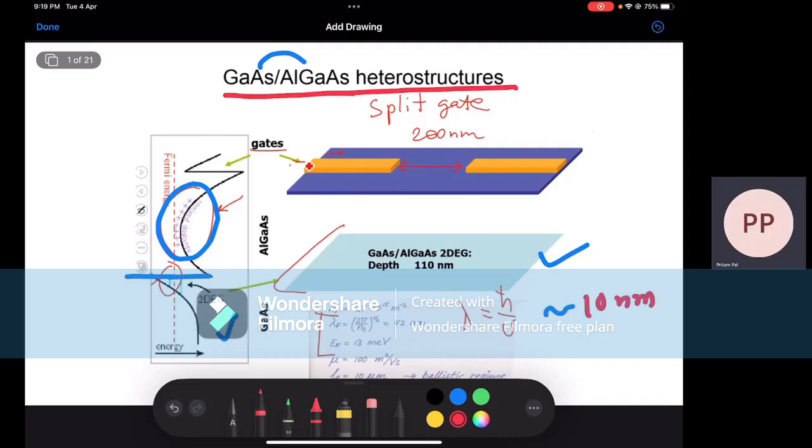So you can think of it as the size of the wave function of an electron, and that is the scale on which single electron wave properties should manifest: tens of nanometers, meaning thousands of lattice sites. Thousands of lattice sites also is one electron, right? And then 5,000 in dimension tells you the doping corresponding to the number of total atoms.